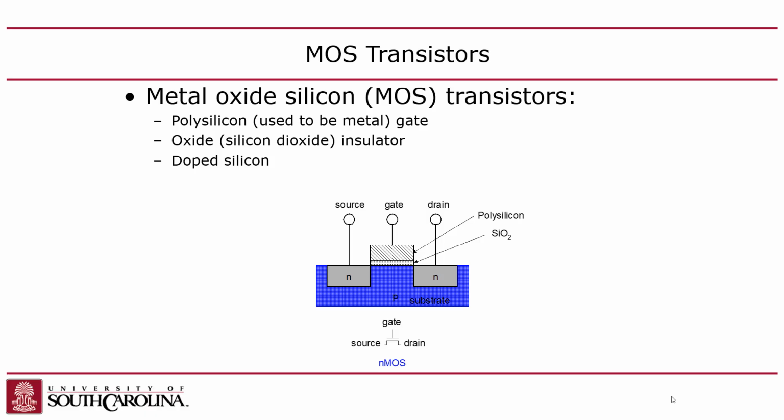So what ends up happening here is that the top of this capacitor becomes the gate. And if I put a voltage on this gate, remember I told you that in the P, you've got holes, right? Lack of an electron, so it's positive charge carriers. But those are the majority carrier. There's also minority carriers.